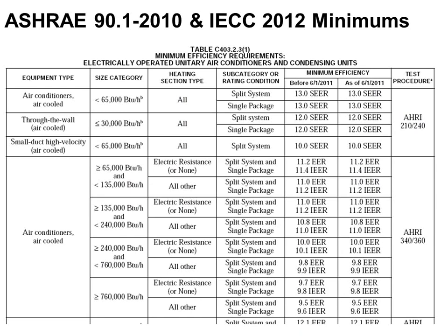So if I look at a 10-ton unit, which is 120,000 BTUs, right? I'm over in this range over here. What do I have to do from an efficiency standpoint? Let's assume I have a gas-fired rooftop because that's the majority of the market. So what do I have to do? I have to have 11.0 EER at a minimum and 11.2 IEER. That's what I've got to do at a minimal absolute low end.